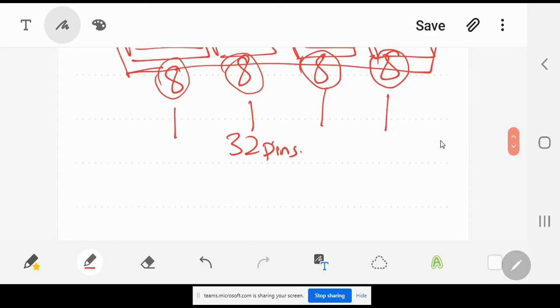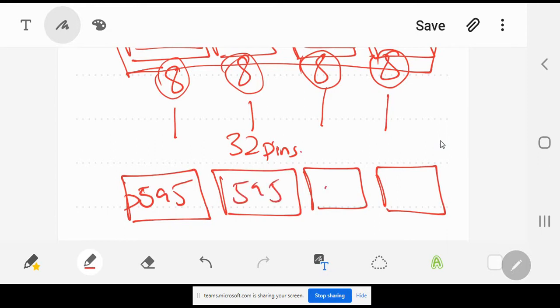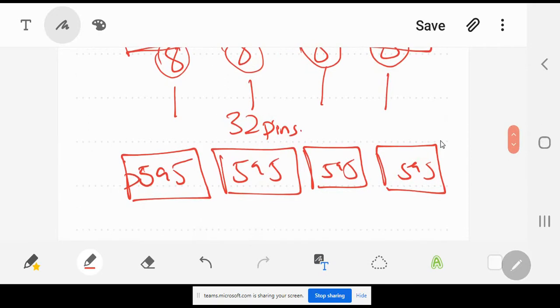So what does the 74HC595 do? It is a small IC, I am just going to write 595 here, and we are going to connect 4 of these ICs in such a way that it will take serial data in, which means serially, just like your hard disk or USB, how does it take data on one wire?